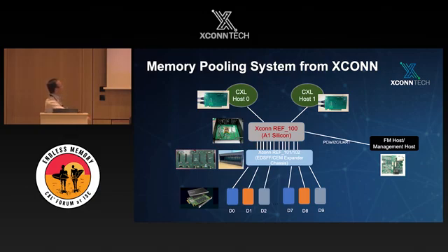We have also built some PCIe CEM slot expander or EDSFF expander boards to enable the downstream ports to be populated with many more CXL memory devices. And on the management host, we use a small board powered by an ARM processor, running all the fabric manager management software.